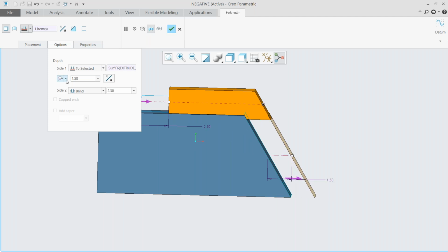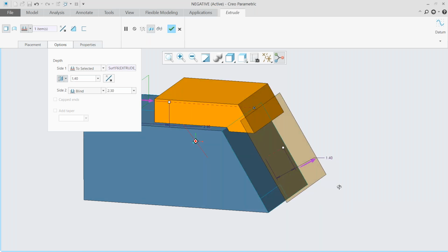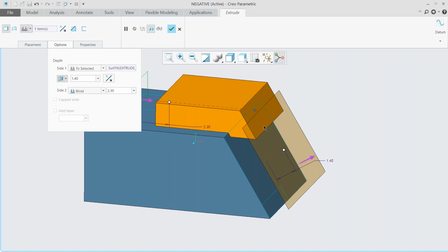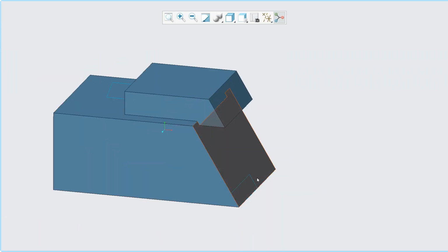This is going along the extrude direction, versus this, which is still keeping its reference to that. It's almost like the system creating an imaginary surface for it to go to, rather than you going to datum and then creating a new plane there. Okay. This works on revolve features as well, right?